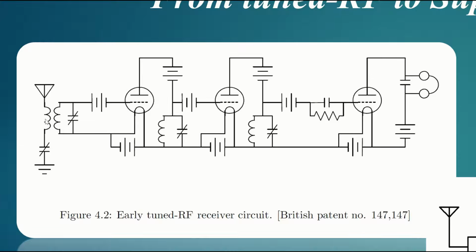The energy in the inductor is coupled over to a second LC network or bandpass filter. And then the signal that exists between the top and the bottom of that is applied between the grid and the cathode of this ancient vacuum tube technology, modulating the current flow through here, and then that is developing a voltage across this LC network or bandpass filter, and so forth and so on.